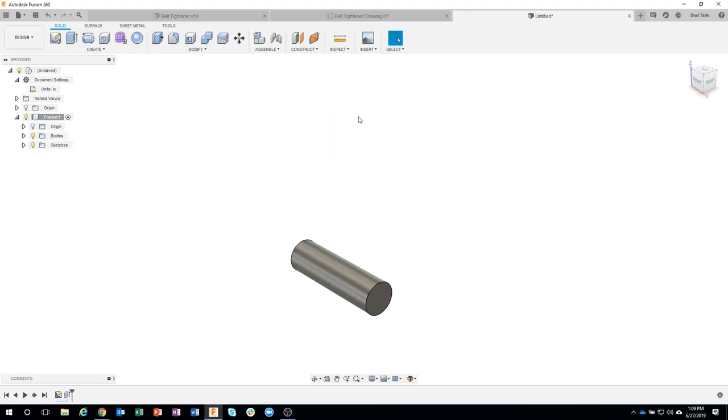And I wanted to extrude that top circle. Well, all it did is, under my sketches folder, you'll notice that the light bulb next to my sketch is turned off. I'll just go ahead and click on it to turn it back on, and now we can see that sketch. And again, another reason I like to use components is you can see how well organized this is. So underneath that component is its own origin, the body, and the sketches that have to do with this particular frame component. Okay, so I'm going to do the exact same thing again.